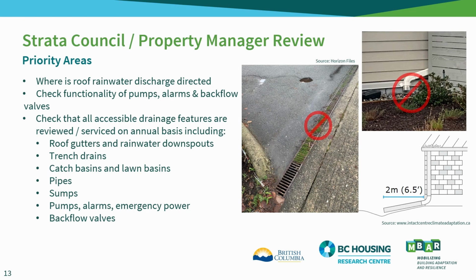Next, check the function of pumps, alarms, and backflow valves to ensure the systems are in working order. Additionally, all accessible drainage features should be checked and maintained on an annual basis. Sumps often become buried within landscaped areas. You may need to consult original design drawings in order to find and maintain these important elements.